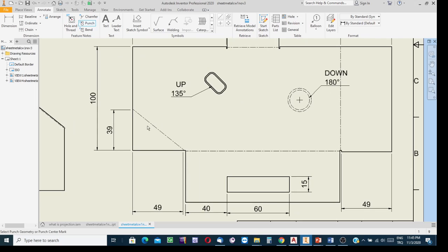How about the bending and bending angle? Well, clicked on, for that purpose, bend button, and then indicate these lines, path lines. Then, well, Inventor will add this technical note saying that to be able to have the object in its final form, this corner is to be bended 90 degrees, rounding radius is 1 millimeter in the down direction.